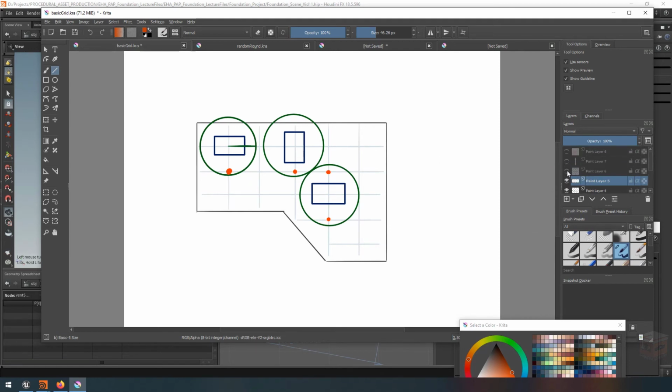Now in this case, we are using the center point of these objects. We're not actually measuring the outside of our mesh. We're not copying our mesh onto our points and then measuring if the object might be close to the border of the mesh. We are checking the center of the mesh. This is not as accurate as checking the outside of the mesh, but it is definitely faster. Okay, and that's what I'm going with here. In this case, these objects are simple enough that I don't have to worry about this. Now in this case, if the object down below here is inside of the range of the object above, then it won't be allowed to be placed. That's basically the simple rule here.